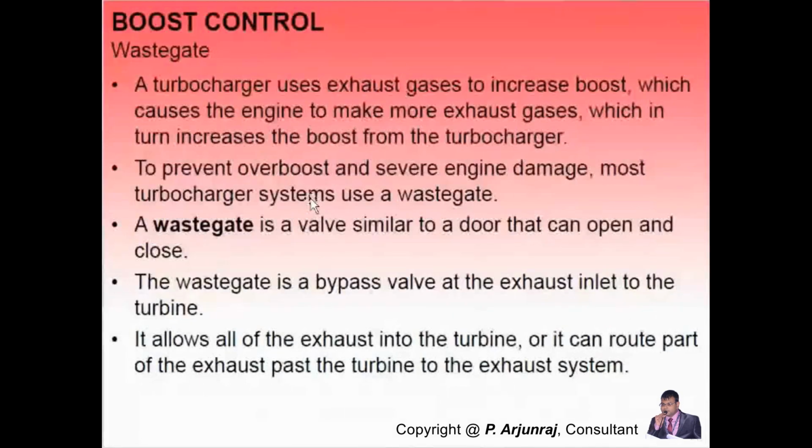So here you need to understand a very important thing. The boost pressure should not be too high, or too low also. So here we use the system called wastegate. Why do we need to use the system called wastegate? This will help the turbocharger to prevent overboost. Even when there is overboost, it is a problem, because it will strike the turbine and cause severe damage also. To prevent overboost and severe engine damage, most use a wastegate. This is the main reason, to avoid the overboost. That is very much important.